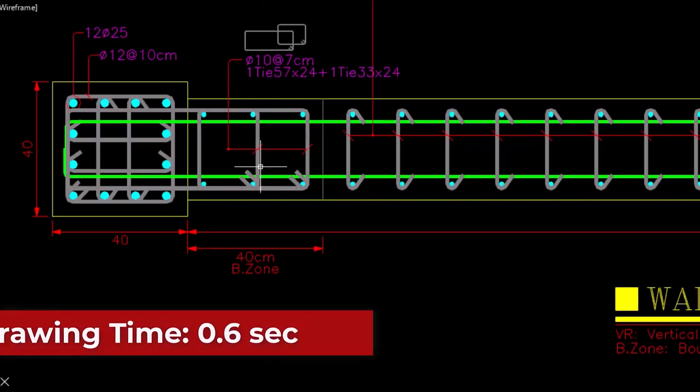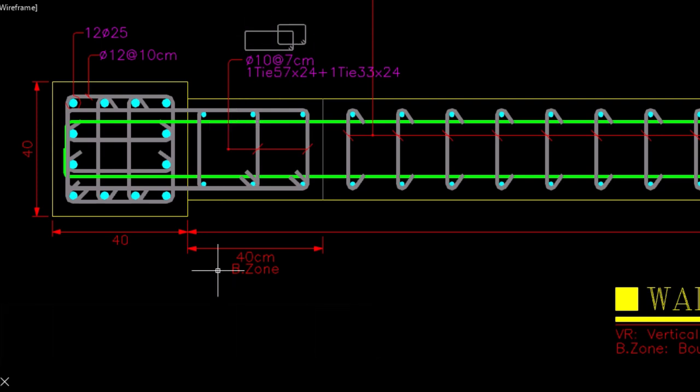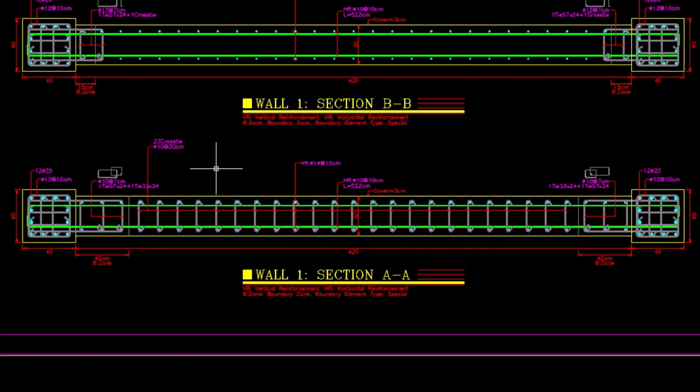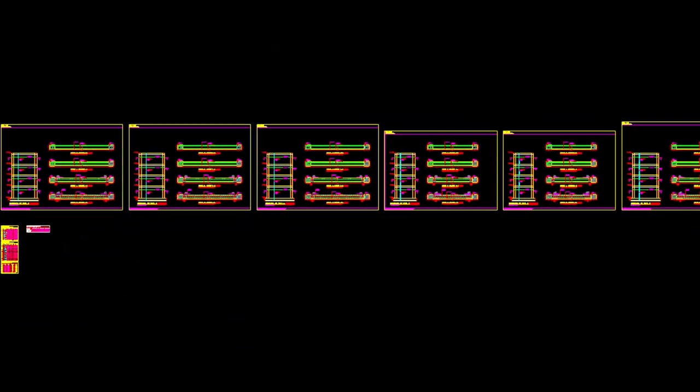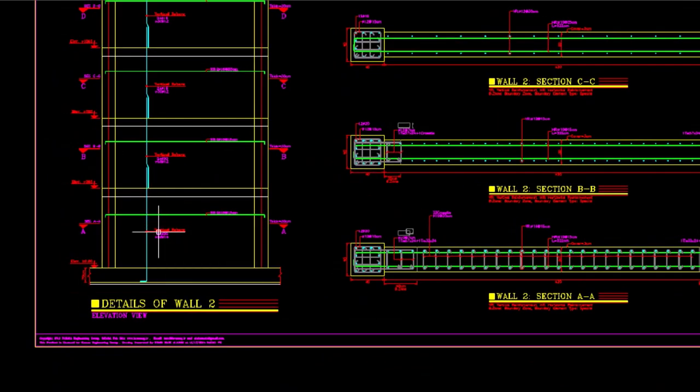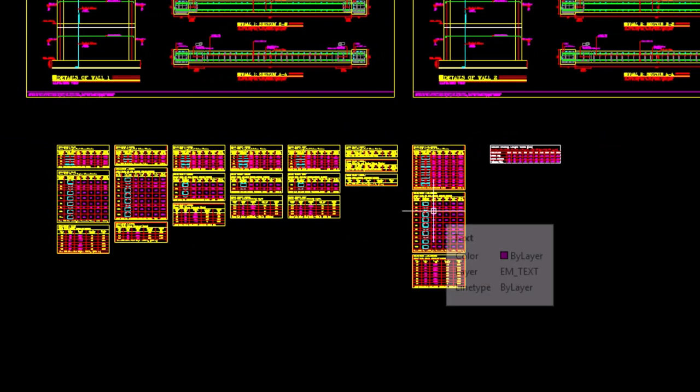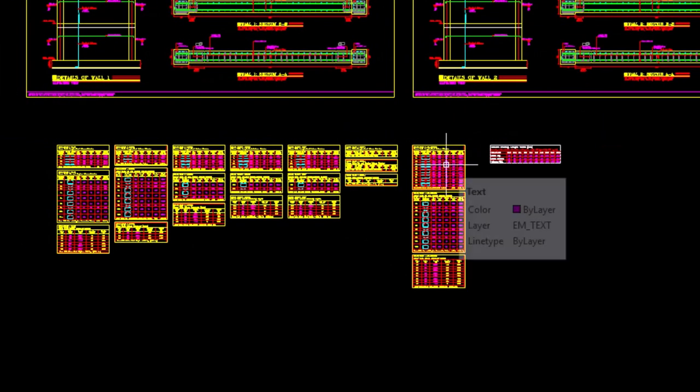Chain stirrups, including the stirrup details, the band length, the type of rebar, the exact pins, and all the wall information, along with an illustrative elevation view of the entire wall, and again the complete list of bar schedules which are generated simultaneously with the detailed drawings.